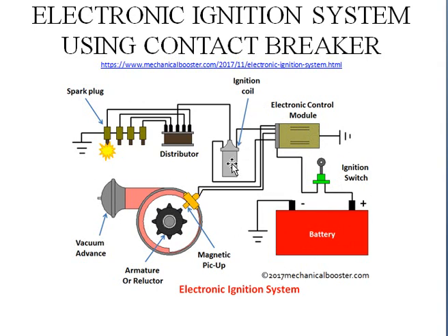This is the ignition coil used for igniting the spark, and this is a distributor to distribute the spark evenly. So here is the spark plug. Here you have a positive electrode and negative electrode, and because of ionization of the gases, the spark will come. It means as there is a small gap between both the electrodes, because of the resistance offered by the gas, the spark will come.